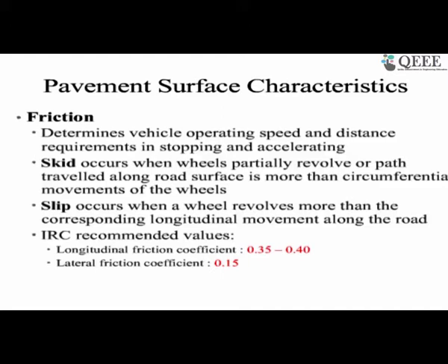As per IRC recommendation, the longitudinal friction coefficient is about 0.35 to 0.4, and the lateral friction coefficient is about 0.15. The point to be noted here is that it's the same pavement, same tire, but the lateral friction coefficient is quite low.